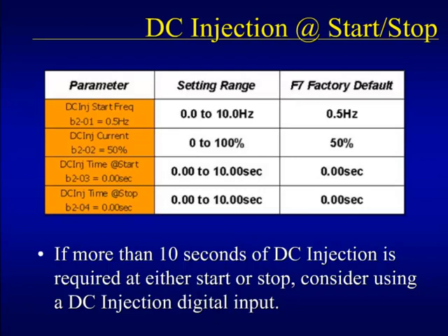If more than 10 seconds of DC injection is required at either start or stop, then using the next type of DC injection braking, a DC injection digital input, will be more effective.